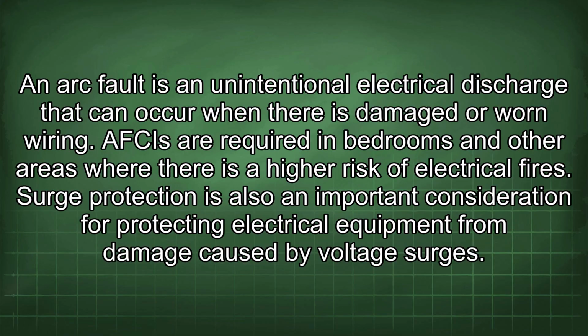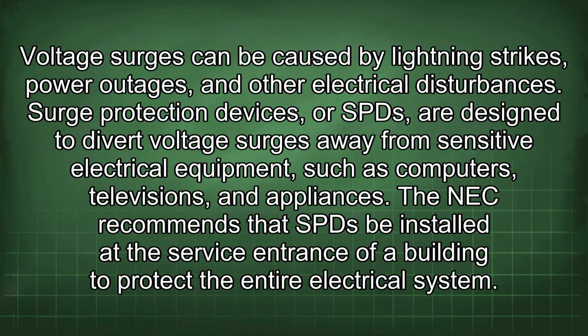Surge protection is also an important consideration for protecting electrical equipment from damage caused by voltage surges. Voltage surges can be caused by lightning strikes, power outages, and other electrical disturbances. Surge protection devices, or SPDs, are designed to divert voltage surges away from sensitive electrical equipment such as computers, televisions, and appliances. The NEC recommends that SPDs be installed at the service entrance of a building to protect the entire